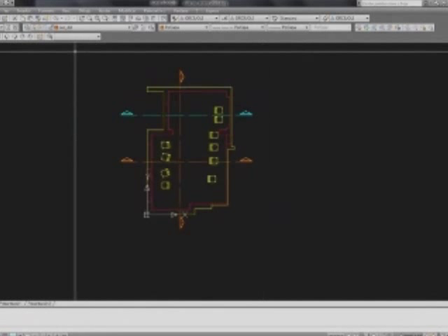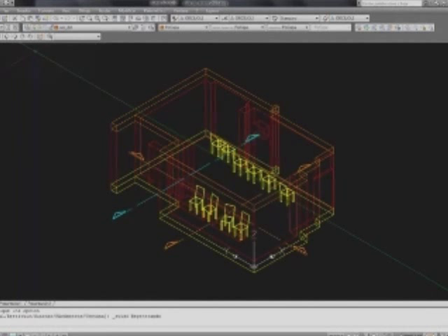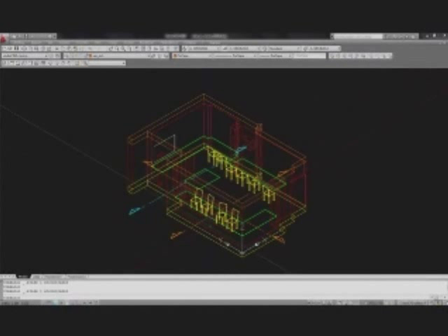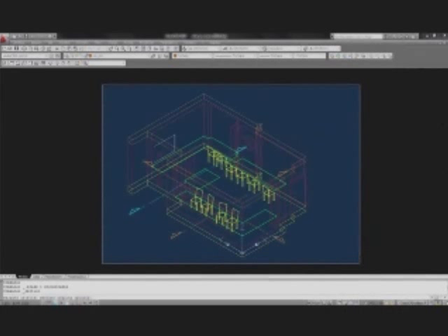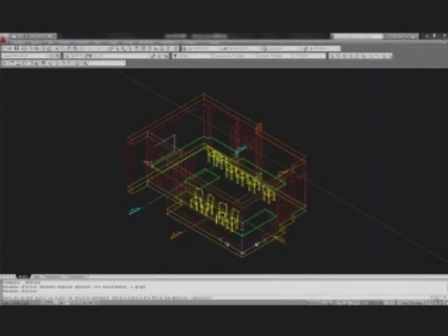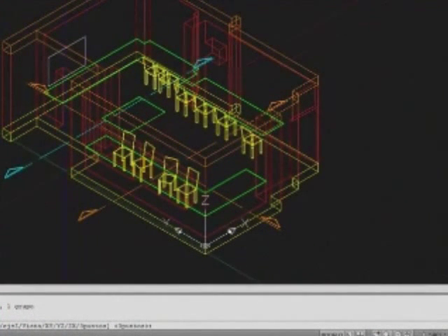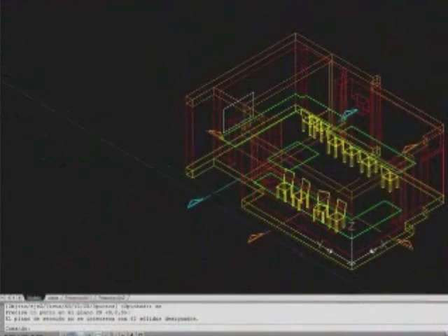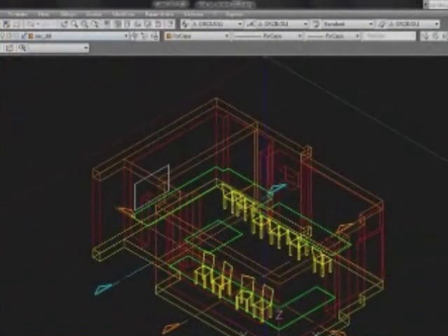I can also see my project from some isometric view, like this one. And also I want to section. So coming back here, we want to generate a section. We select everything, all 3D solids, and the plane in this case is ZX, because it's through this line, the Z and X plane, and we define the point, that is this one. Great. So we have here our result.